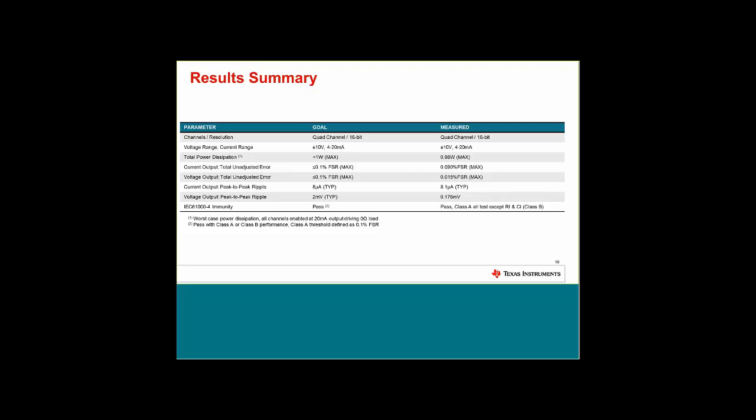It's actually quite common because the band of interest for conducted immunity goes down to bandwidth that is quite common for precision instrumentation to be able to react to. Meanwhile, for RI, this starts at very, very high frequencies. So I'm a little surprised to see Class B for RI, and to be honest, I think that was the artifact of the test setup.